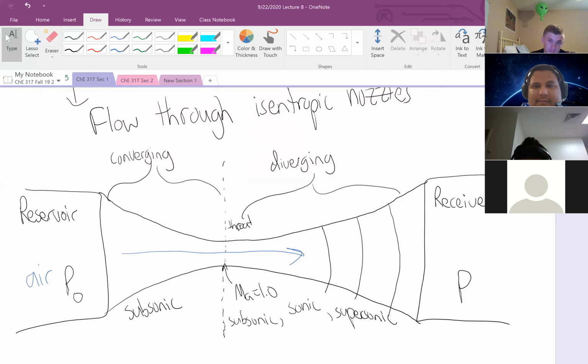Does this only apply to nozzle design, like with the subsonic, supersonic? In terms of confined flow, it only is possible in an isentropic nozzle. When we consider adiabatic and isothermal systems, the sonic velocity represents the barrier that constitutes choked flow. You're never going to be able to achieve sonic and supersonic flow in typical traditional flow systems.